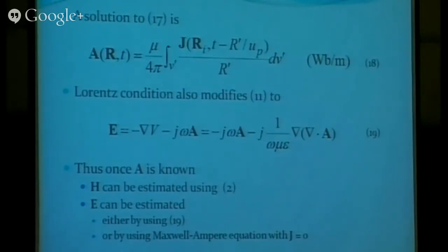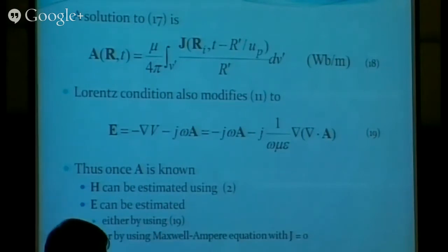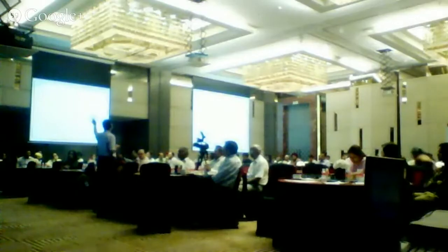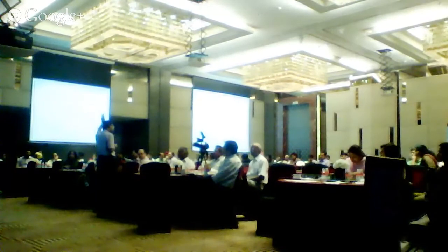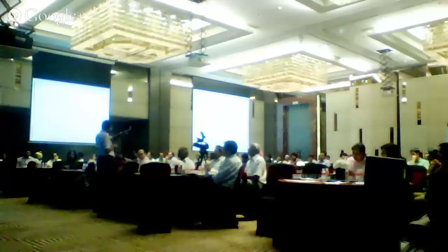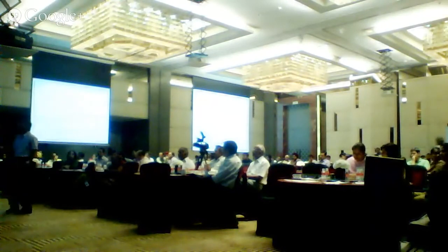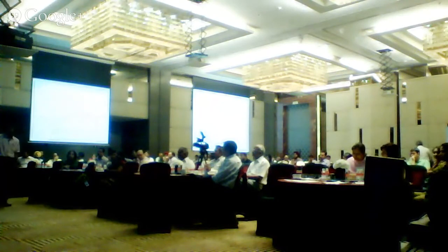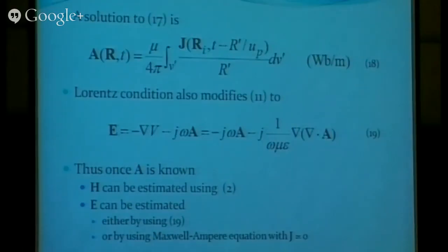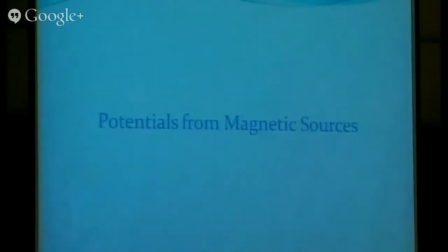And again, a phrase that is very common in electromagnetic papers: source-free region. Normally when we estimate fields in the far field zone, sources are 0. A source is, for example, a mobile tower, an antenna which sits kilometers away. So sources don't exist in the area in which we are calculating the fields. When we consider the Maxwell-Ampere law with source 0, then J is equal to 0, and it is also possible to calculate the electric fields. So these are the two potentials.